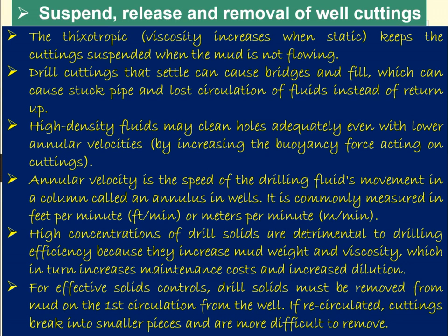If the cuttings settle down below, it will be very difficult to take them out. That is why this thixotropic property helps the cuttings to be suspended when the mud is not flowing. And when flowing starts, since they are suspended, it is easy to take them out.